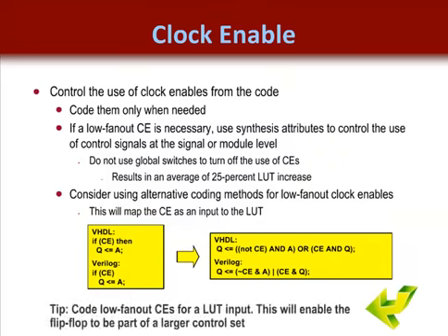So remember, code your low fan-out clock enables to drive the LUT inputs. This will enable the flip-flop to be part of a larger control set and give the tools more flexibility to meet your timing objectives, and you to have a better chance to make your high-performance design.